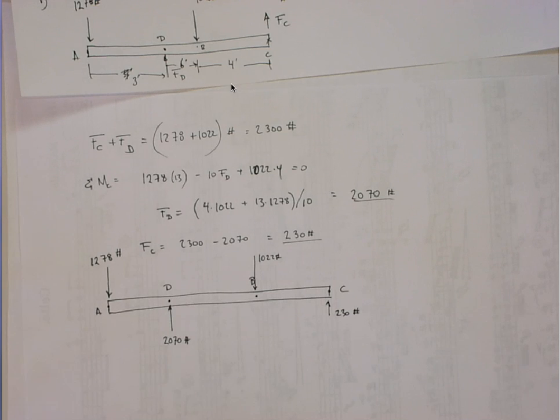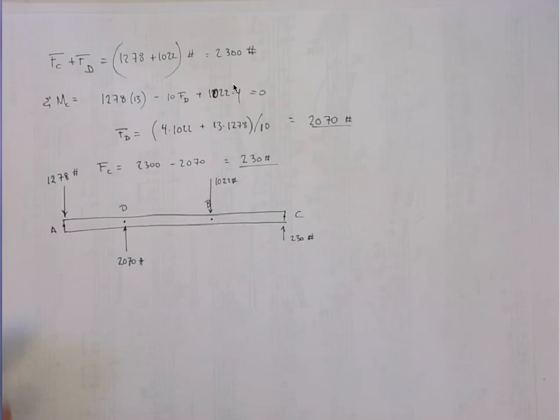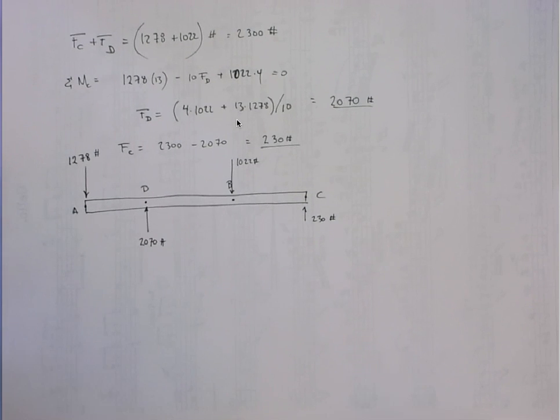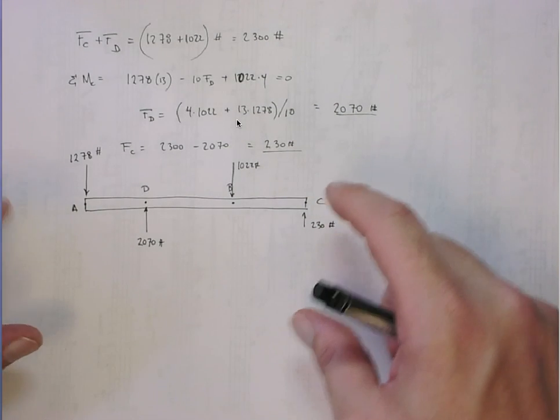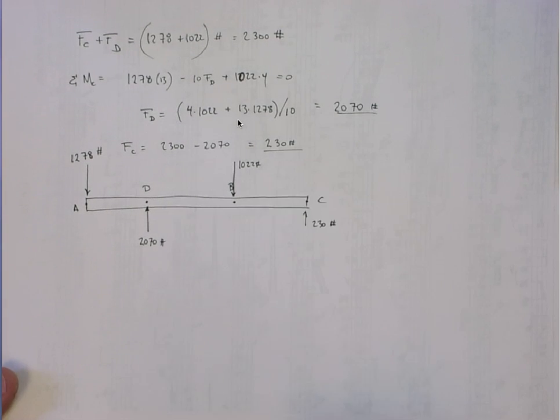All right, so now we need to compute the bending moment diagram. This is nice. It's got some point loads, so we can actually kind of do this graphically, I guess. Again, the moments have to vanish at the ends. It's not built in on either side, and there's no externally applied moment. We're assuming the trailer hitch is pinned, right?